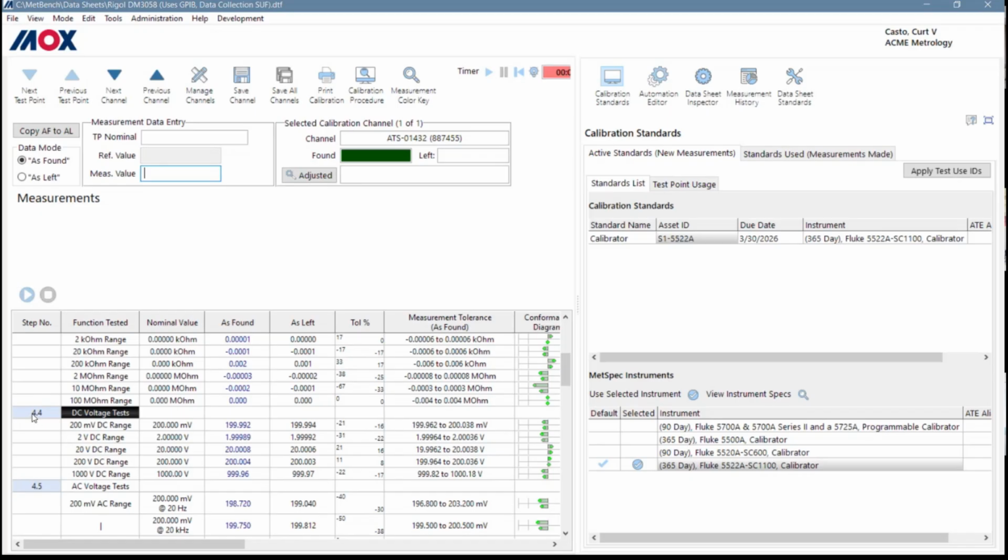And again, as Rob showed you with his Fluke 77, you can see here, these are places where they're teal. And by the way, all these ones above are all zero tests, so I'm just skipping those. That just has you connect a 4-wire short and does all the zeros on all the functions, because when they're automated, you want to minimize the number of connection changes you have to do. Okay, so let's just go ahead and run this.